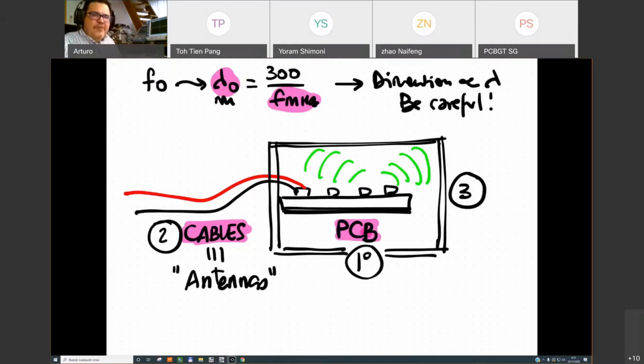It is when you are working with very low frequency magnetic fields. For example, DC, 50 hertz, 60 hertz, 100 hertz, 120 hertz. With these kinds of frequencies, magnetic fields are very difficult to control with a typical metallic material. You need special materials like mu metal.